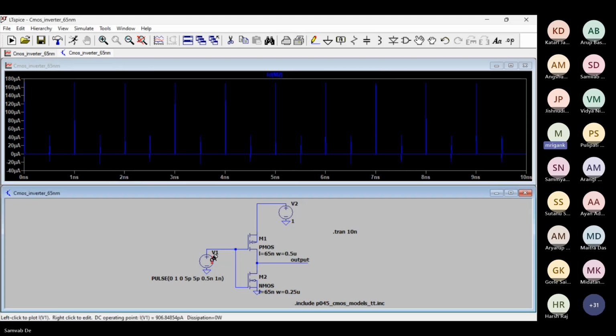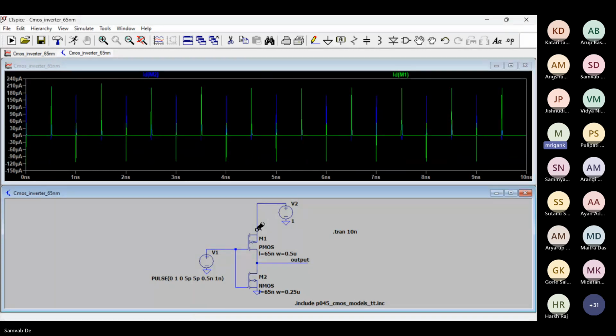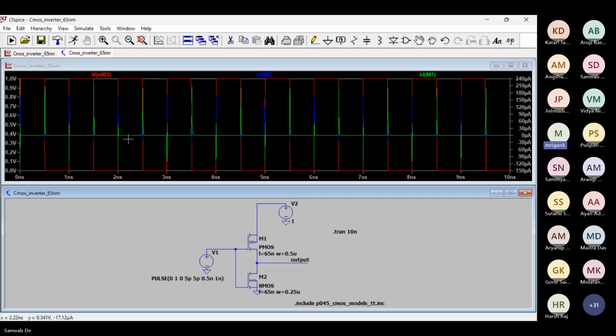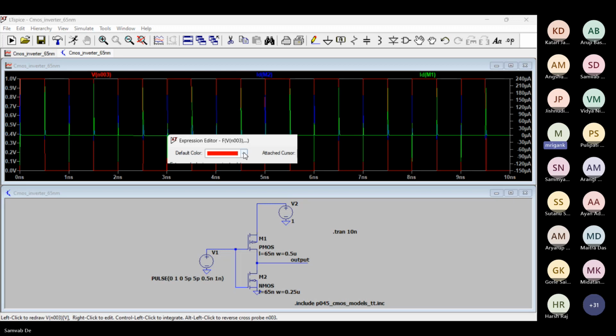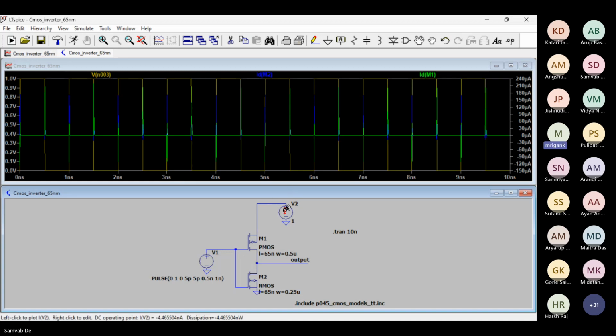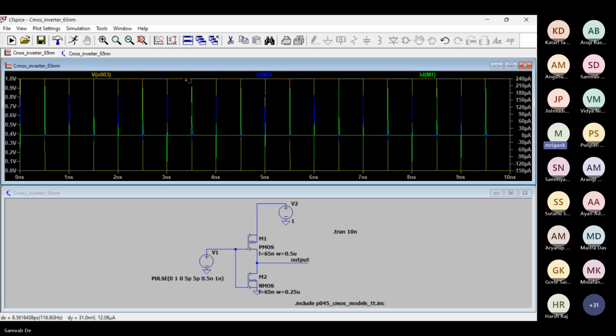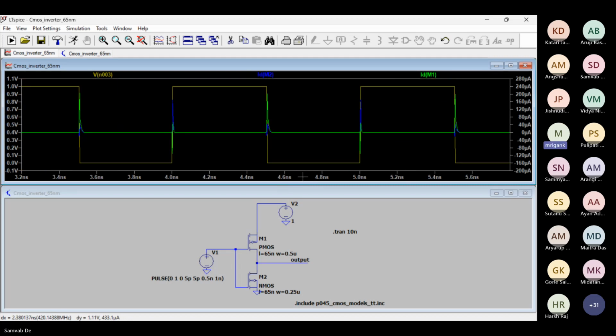Yes, that depends upon the overall current direction. The way he is plotting the current, it is the source terminal current for the PMOS and the drain current for the NMOS. If you look at the condition where we have the NMOS current, in the transition period ultimately both currents should be in the same direction, and there may be some negative current because of charge sharing.